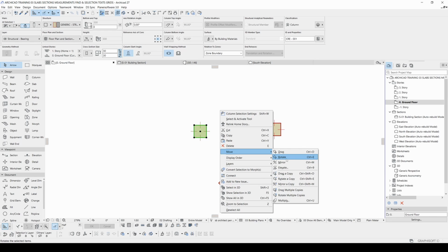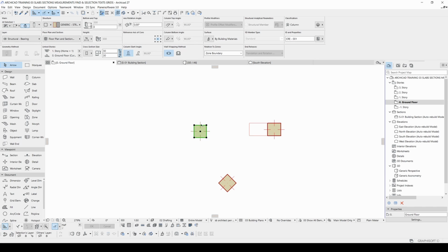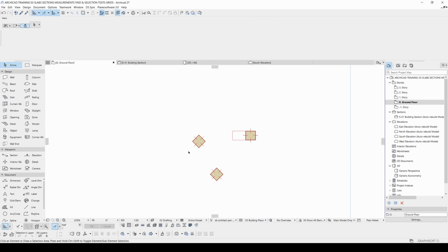Or you can just use your shortcut. I've changed it to Ctrl plus E. Just like this. First we will hit Ctrl plus E or any shortcut you determine. After that you will select your rotating point. For instance, this point. You will click your reference point line such as this, and you can rotate. And second, last, you can finish.